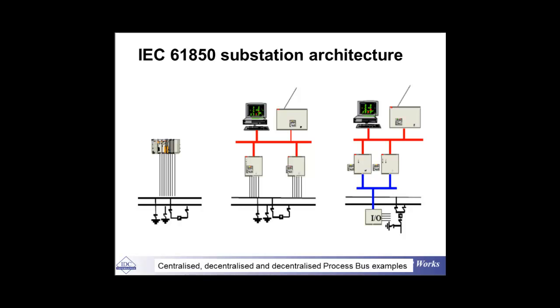If it is decentralized, it is not as bad as that, so you have a little bit more relief and comfort in here, but at the same time, you need a lot more cabling and more devices. You would need some more space. And also, again, decentralized just applies to the process bus. You can see that again there's more comfort in terms of redundancy, but in terms of the work itself, it costs you more, and basically more wirings and more complexity would come with it.